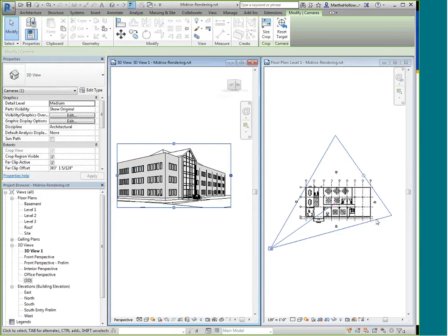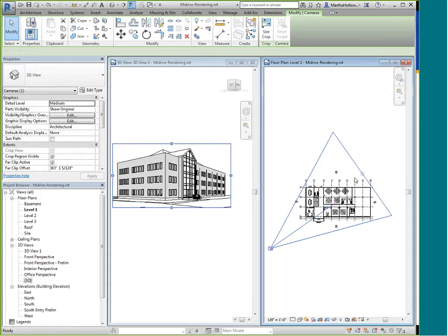And you can see on this side, we just had a change to the field of view. This side needs to be wider, so I can move that out. And once again, the field of view has changed. Now, in this particular perspective, here's my target. Here's my far clip plane. Just want you to see what happens if I move that. I'm getting some of my building over here chopped off. So that's what the far clip plane does for you.